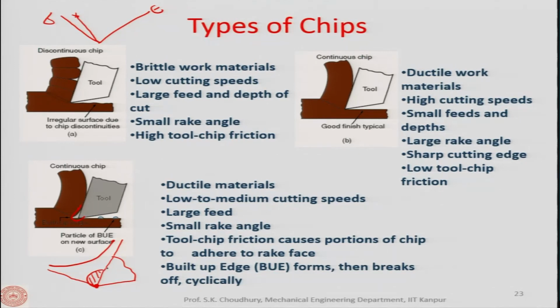So the stress is maximum here, and the resistance to the shearing of this, when it is sheared off, will be maximum along this line. Whereas, as you go inside, the hardness will be less, because of this curve, as you can see. So the resistance to the shearing will be less along this. Let us say this is A, this is B, and this is C. So the resistance along ABC will be less, because the stress is maximum along the AC. So when this piled up built up edge breaks, it will break along ABC, and not along the AC.